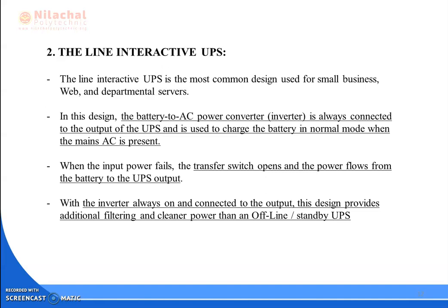In this design, the battery to AC power converter, that is, the inverter, is always connected to the output of the UPS. So the inverter is the main source from which the user or the computer or the system runs. So how is it possible?